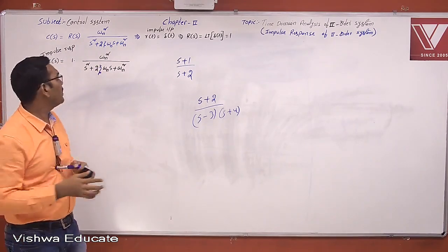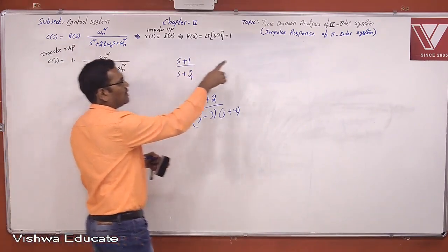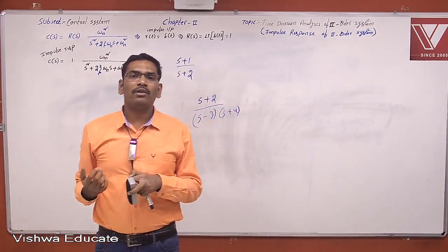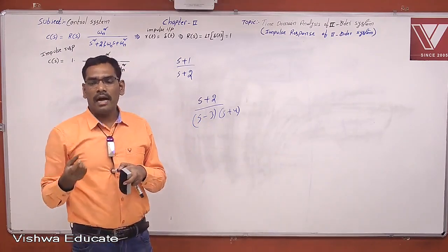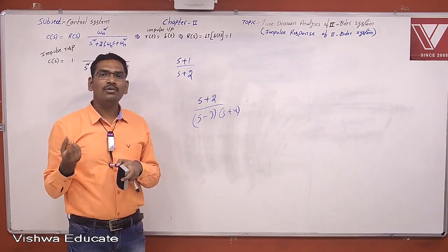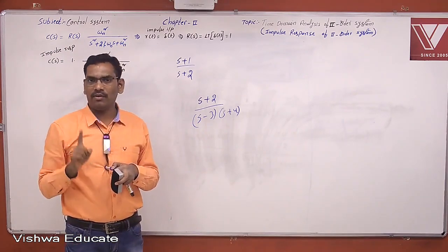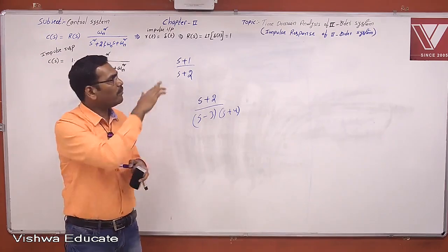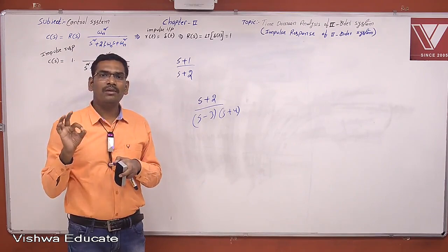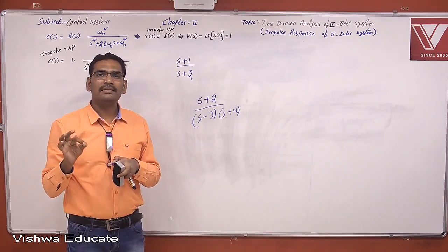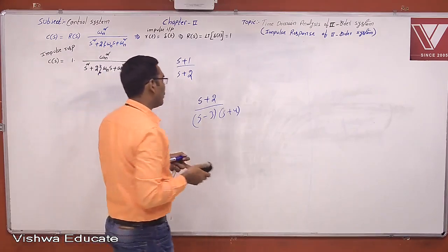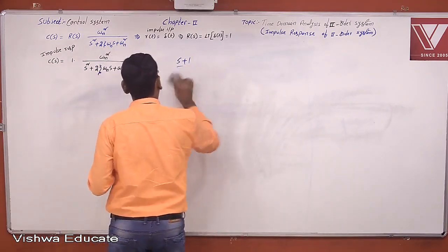So now we are at the theoretical analysis, because this is the impulse response. In the theoretical analysis itself, you can find what the suitable damping factor zeta should be, such that it is useful to design the best second order system. One important question is not only the time domain analysis, but also finding the suitable damping factor zeta so that we can get a good response of the second order system. Keep that point in your mind and we'll start the analysis.